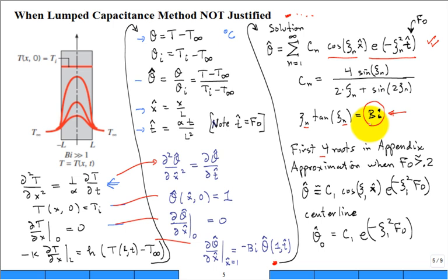All right. If you then only really want to use this equation for large Fourier numbers, and that's not really that large, it's just Fourier numbers greater than 0.2, what they find is these terms, second, third, fourth, fifth, decay much more rapidly, and they go out of the equation. You only have one term that dominates the whole solution, and so it just goes to a one-term approximation when the Fourier number is just greater than 0.2.